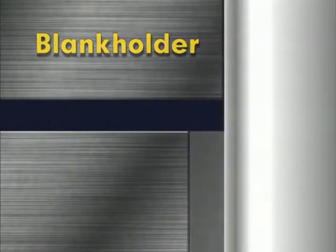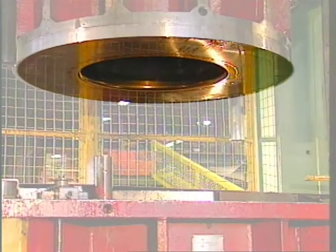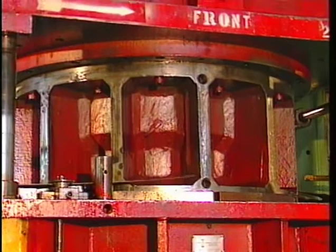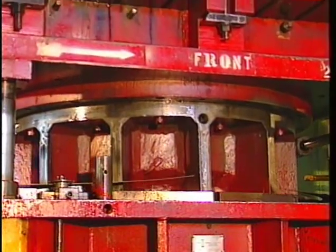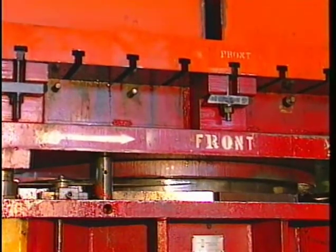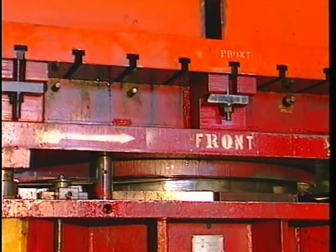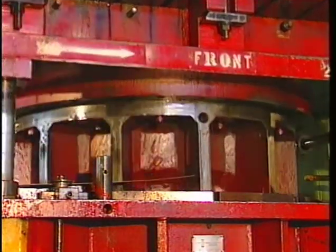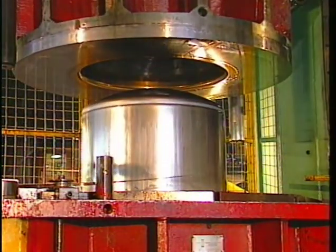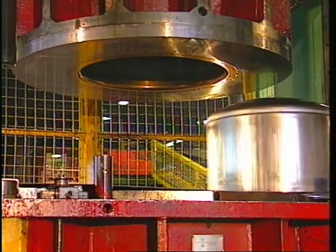On most forming presses, the blank holder is an outer ring through which the inner ram or punch passes. The blank holder holds the workpiece against the draw die to control metal flow as the punch forms the shape. In practice, the blank holder must exert less pressure against the blank than the punch, so metal can flow into the die, yet it must exert enough pressure to prevent wrinkling.